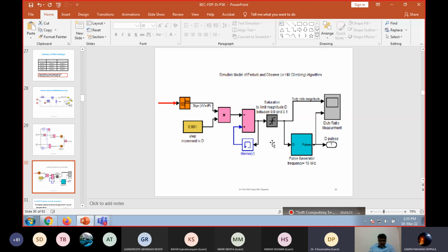If it reaches the value 1, then 1 by (1 minus 1) is equal to infinity, so the output voltage is equal to infinity. From the converter, we would get an output voltage of infinity. It is not recommended, so it is kept less than 0.9 only.